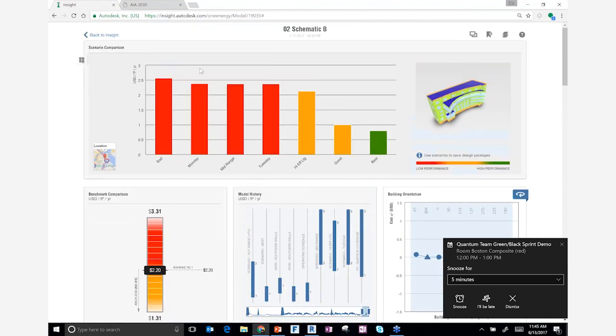So that's essentially the main components of Insight, and the whole idea is that from the very earliest stages, when you have something as simple as a massing model, without even any glazing applied, you can analyze that and you can quickly see the cause and effect of glazing, of shading, and of every other parameter. Then as you model throughout the design process and start to add specific glazing designs, you can measure that against your goals, continuously tracking, are you doing worse, are you doing better,